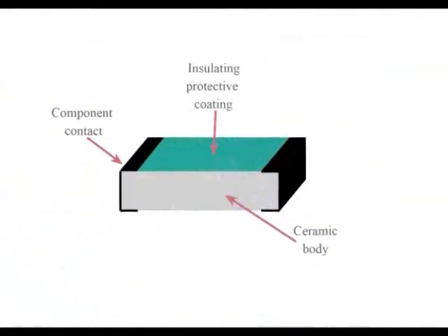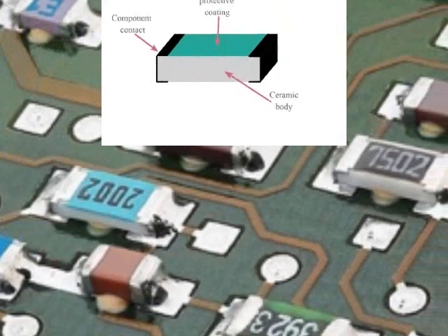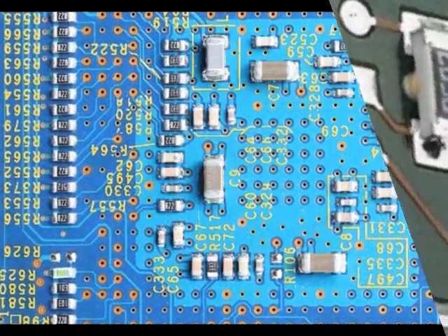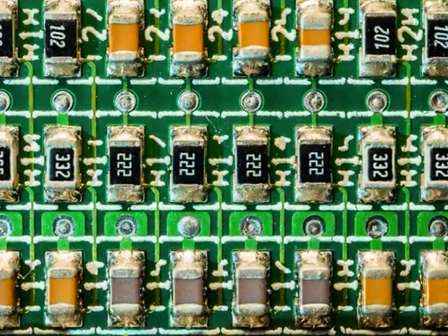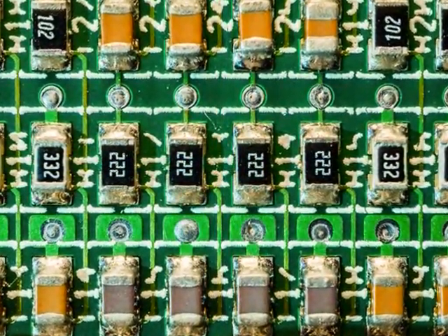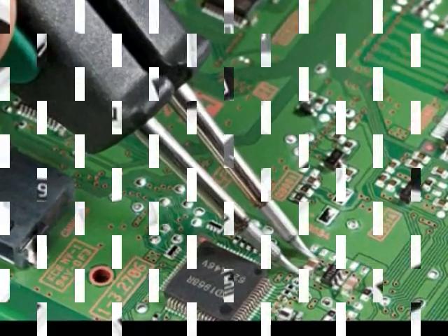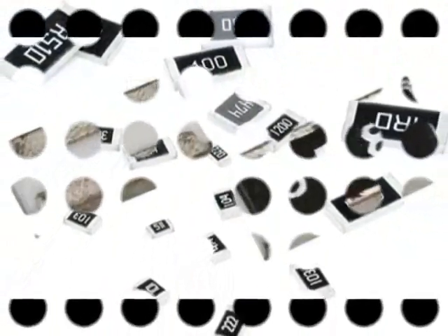The resistors are made of metal and can be printed on the board. The design of this resistor can be done using ceramic or aluminum materials. The resistance can be calculated based on the thickness, length and materials used. These resistors are enclosed using a protective cover with successive layers. Protective coating layers prevent mechanical damage but do not stop the penetration of moisture and other contaminants.